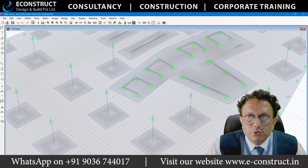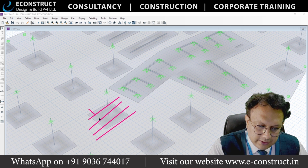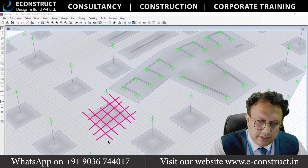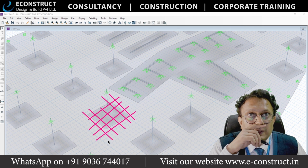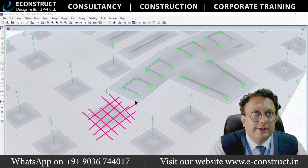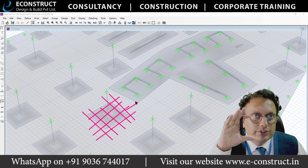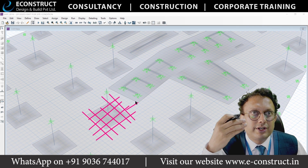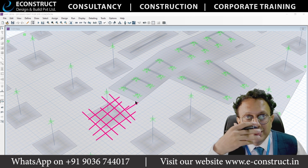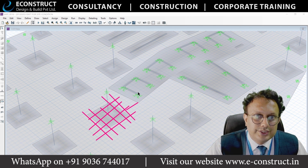But I was getting very heavy reinforcement. Where? Here. Like this. Very, very heavy reinforcement. So to reduce the diameter of this rebar and adjust the spacing, I have to increase the depth, because Mu upon bd square, the moment I have increased the depth, the moment of resistance also will be increased substantially. Understood? Okay, so this is how it is.